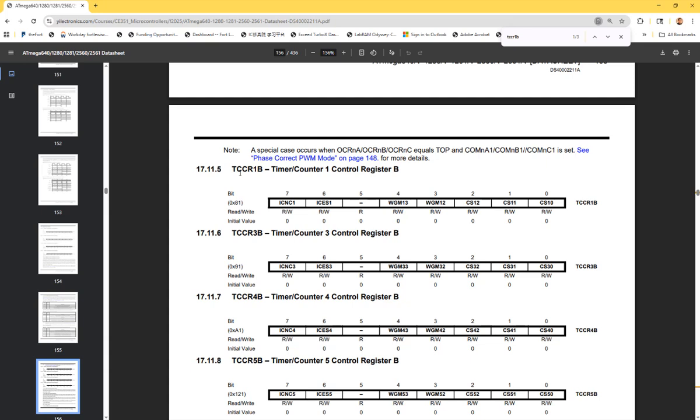We'll cover what interrupts are, but you want to handle multiple tasks at the same time. And you are using some functions and libraries online. You just download a library and you want to use it, but that library is running behind the scenes, taking timer 0 or timer 1, and now you do need another 2 timers for your code, and you're just running out of timers. So it's better to have more timers.